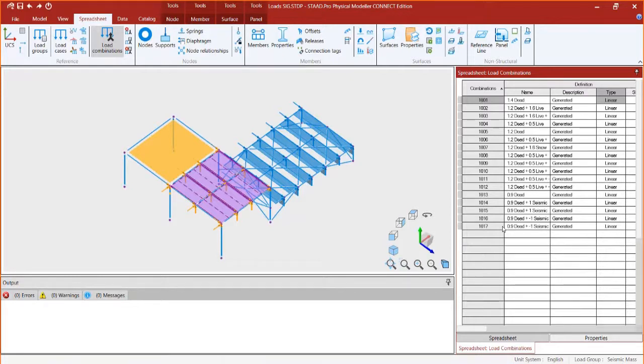I also like to show, however, how to know what load combinations will be generated. So you can basically review them. I think for any structural engineer using any piece of software, you should always thoroughly review your load combinations and make sure everything is as you had intended it to be designed, incorporating everything you were looking for.